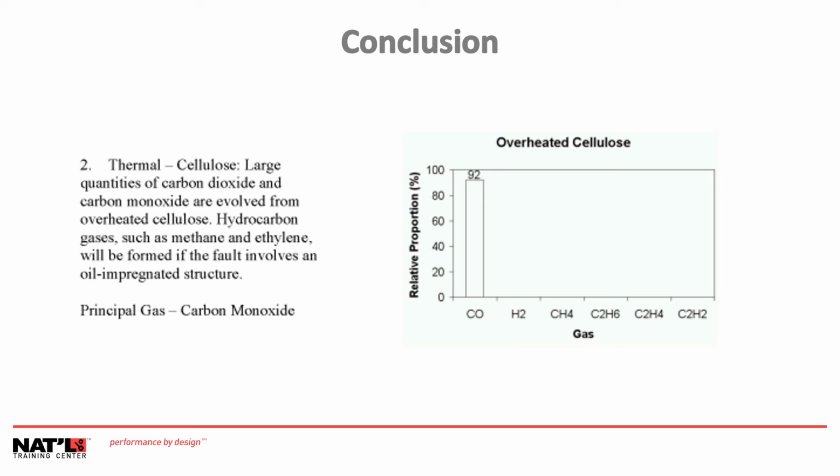CO and CO2 are found in all liquid immersed mineral oil transformers. They are primarily produced by the breakdown of the cellulose and solid insulating material. When transformers are run close to full load, they can continue to produce CO and CO2 depending on the temperature. The static levels and even some increasing levels are not typically a reason for alarm if no other indicators are present. Keep in mind that thermal aging reduces electrical component life. CO and CO2 levels that continue to rise annually can be indicative of and point toward a premature failure.